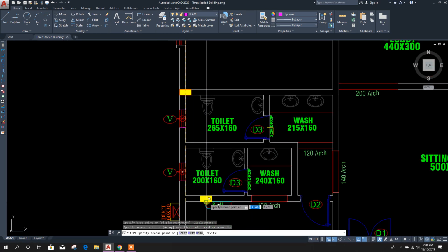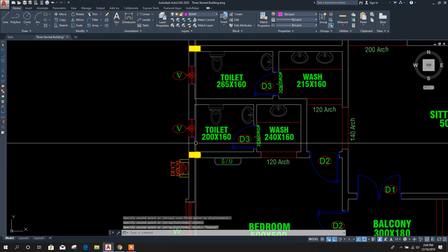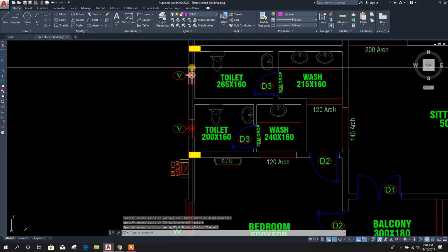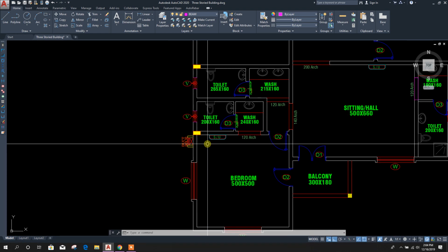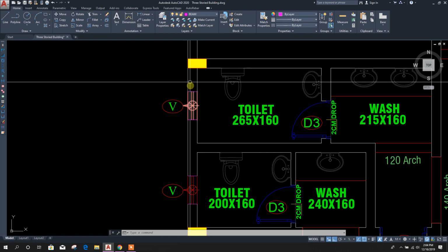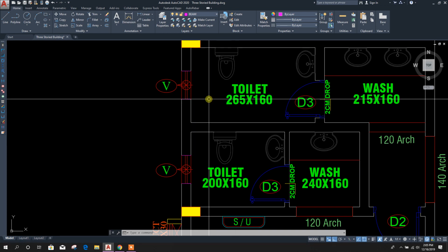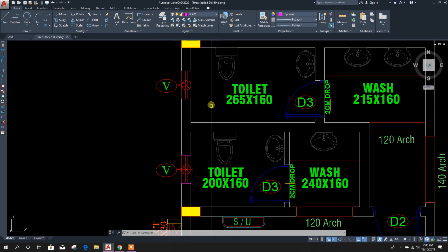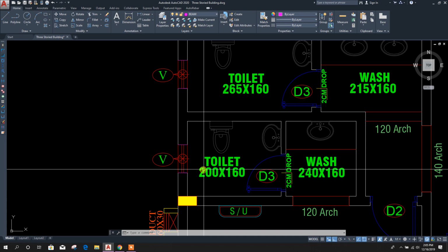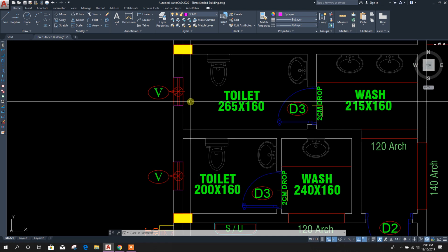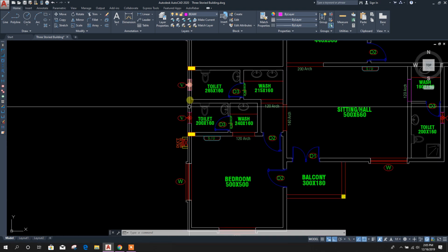Okay, now here column, as here two toilets, so we can put another column here so that this beam can be taken down to provide plumbing pipes easily. In this case, if we make this beam a little bit down for provision of pipes, there will be no requirement for cutting core inside the beam for pipe. Cutting beams and columns is very dangerous for structure, so always better to avoid cutting inside the beams and columns. So this we have provided.